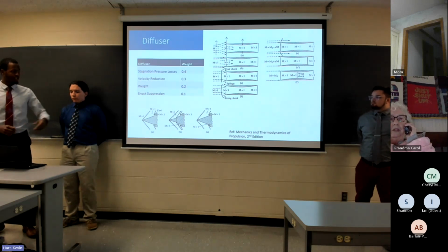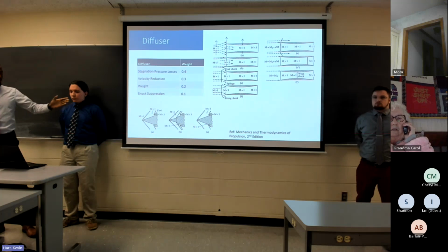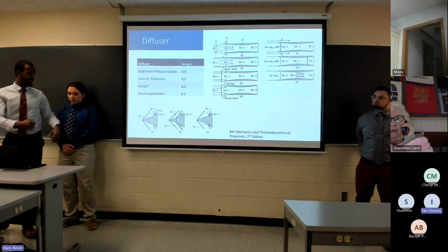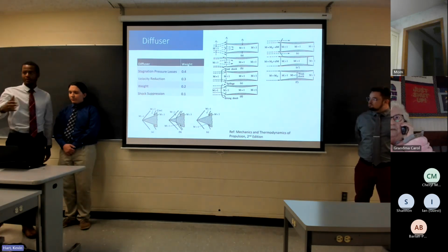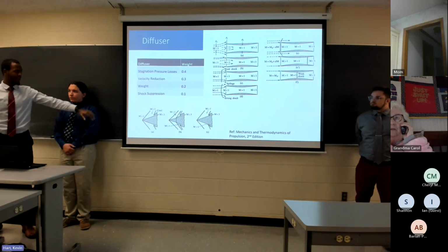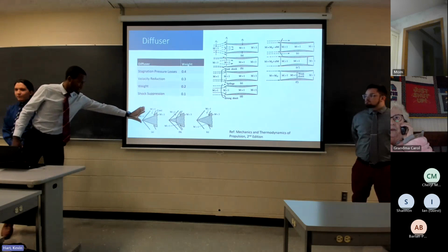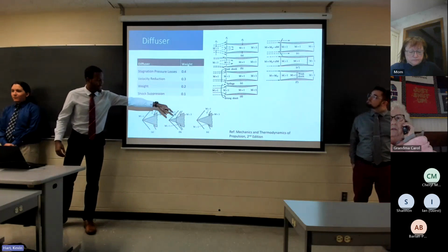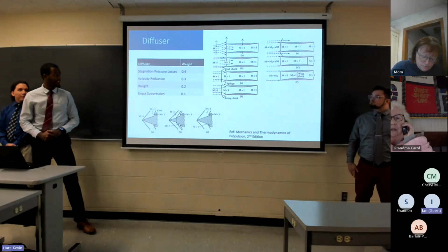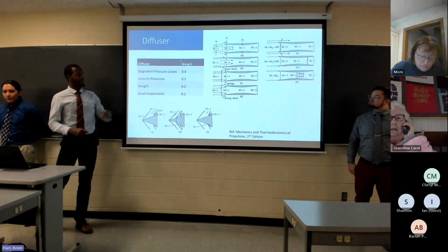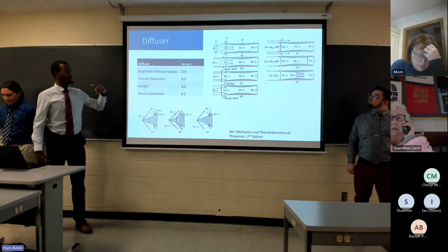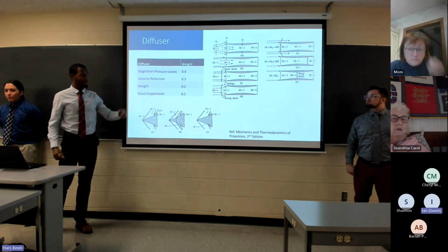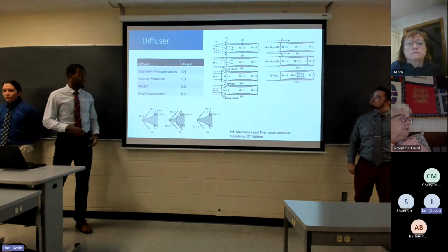First we had the oblique shock diffuser, which is an oblique geometry at the front of the engine that causes the shocks to be suppressed by allowing them to happen before they get to the inlet of the engine. So first you have one major shock and then two smaller shocks, then a series of shocks leading up, and the third one where you have a smaller shock closer to the inlet of the engine. And then we have the reverse nozzle diffuser, where you overspeed your engine slightly to move the shock into the actual diffuser, where it's weaker and less stagnation pressure losses occur.